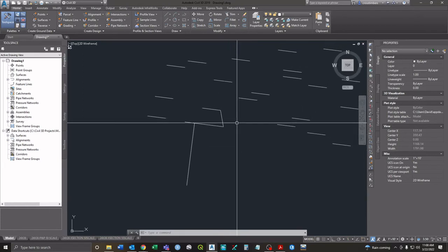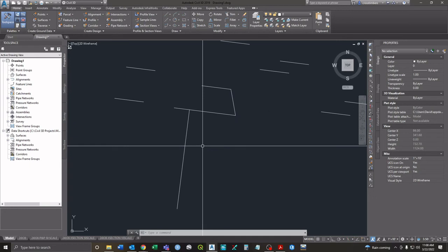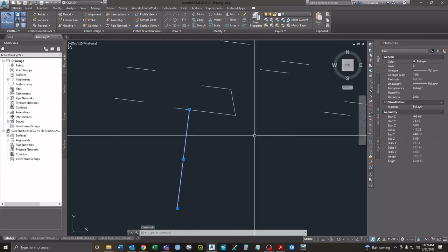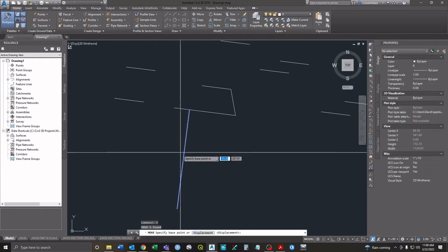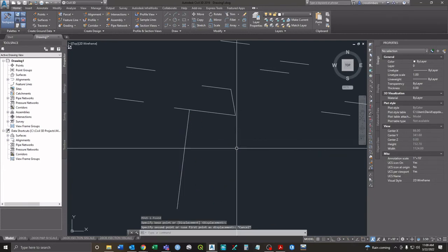Okay, and I guess the last one, which I know you're familiar with at this point, is the offset command, which is pretty useful. I use that pretty often. So again, that's just O for offset. And there's a couple ways to do it. I told you don't generally highlight the object before you pick the command. You can do that. Like I just say I want to move that. So you hit move. Well, now you've already selected the object, but then now the cycle is a little bit different as far as the way the command works. Okay. And sometimes it's good to do that, and sometimes it kind of throws things off a little bit.